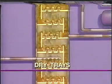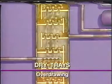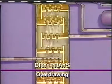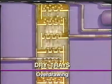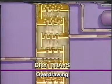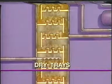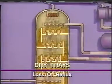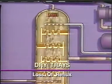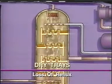Another abnormal operating situation is dry trays. Dry trays sometimes occur because too much liquid is drawn off as side product. When this happens, the trays in a section of the tower immediately below the draw-off point become dry. An interruption in the supply of reflux or insufficient reflux to cool the rising vapors can also cause dry trays.